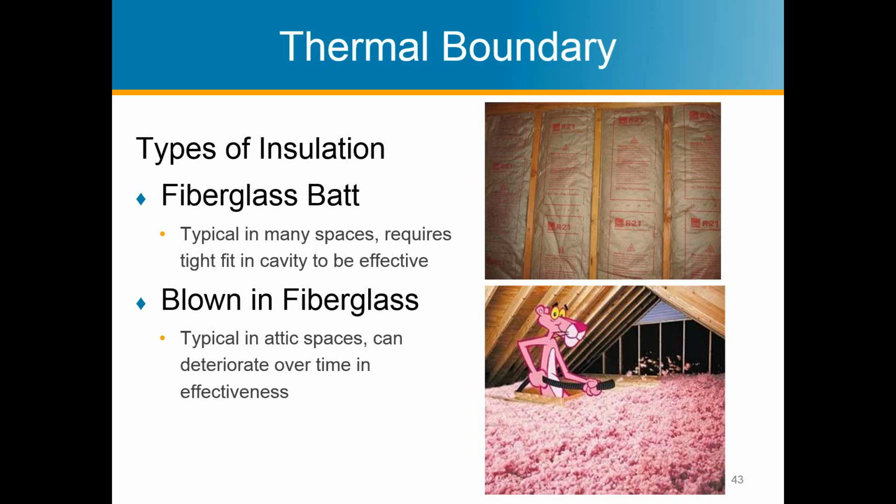Different types of insulation. Fiberglass, there's fiberglass batts and there's blown-in fiberglass. You never get the pink guy, what's that guy, to come up in the attic and blow it in. But the fiberglass batts is what most people do in walls. They are almost impossible to put in correctly, and I don't think these are even installed correctly in the picture. And then there's the blown-in fiberglass too that you typically see in the attic.